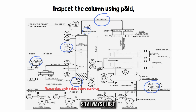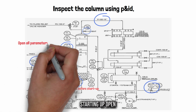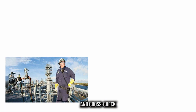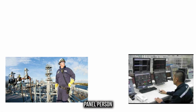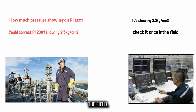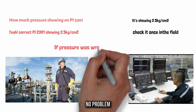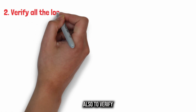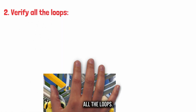So always close all drain valves before starting up, open all pressure and temperature gauge valves, and cross-check with the panel person, like ask how much pressure is showing on the panel for this PI 2301, and they tell you the pressure. Then you check it once in the field. If it's the same, no problem. If there is a difference, you contact the instrument persons to check the indicators, and you can check with the pressure gauge also.